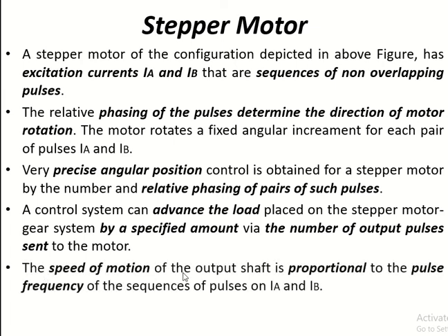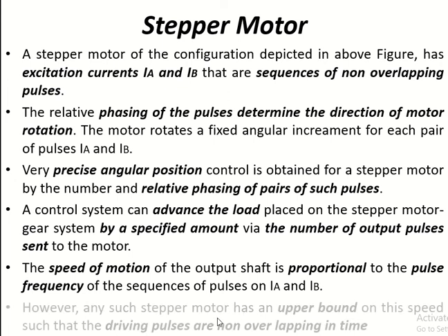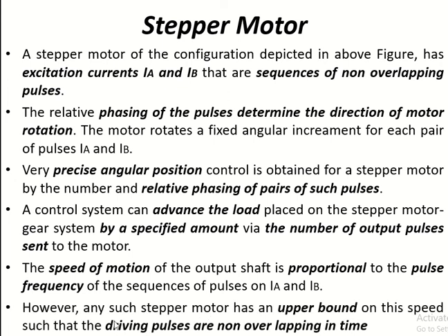The speed of motion of the output shaft is proportional to the pulse frequency of the sequences of pulses on IA and IB. However, any such stepper motor has an upper bound on this speed such that the driving pulses are non-overlapping in time.